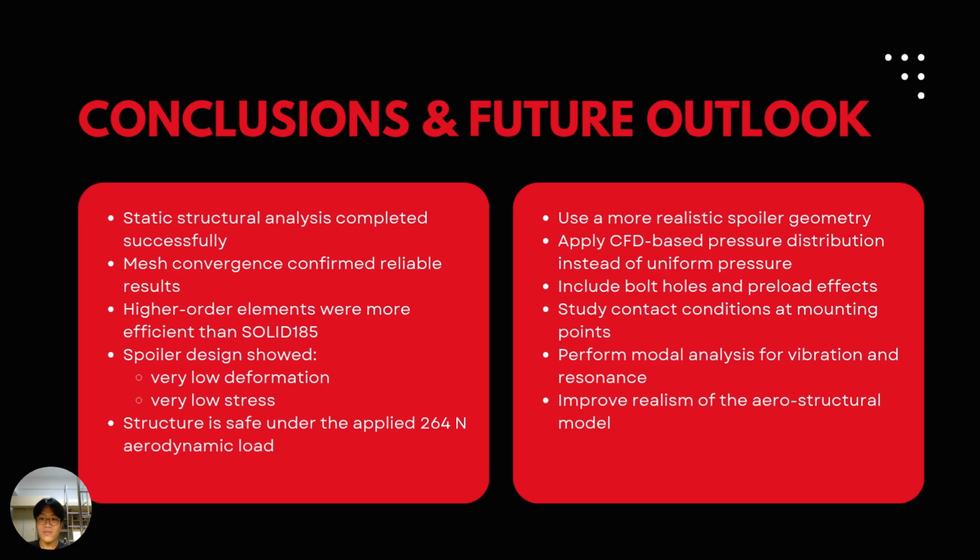For future work, the model could be improved by using a more realistic spoiler geometry, applying pressure from CFD instead of uniform loading, including bolt holes and contact conditions, and performing modal analysis to study vibration and resonance.